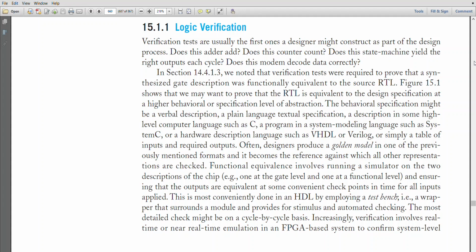So logically you will verify the design, that the 1-bit adder is correctly working or not. But when we go for the actual manufacturing, then you will test the actual device before it goes to the market, to see whether the device is working correctly or not. So one is done on paper and the other is done on the actual ground. Verification is done on paper and testing is done on the actual ground. This is the basic difference.